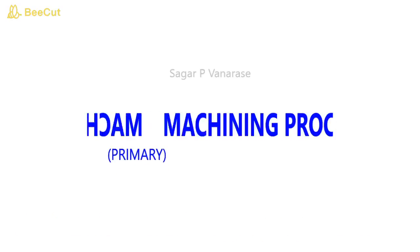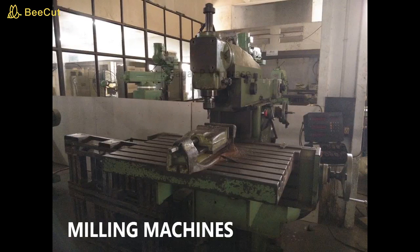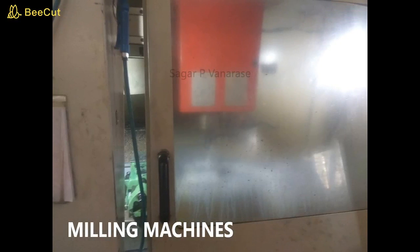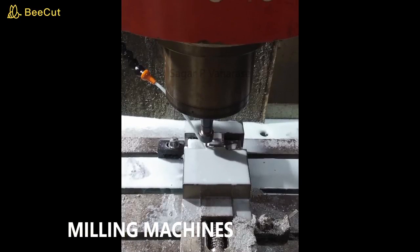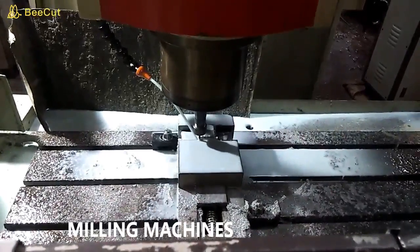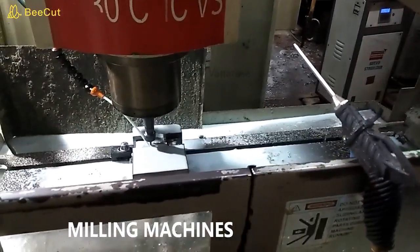The next part is the machining process, starting with the primary machining. Milling machines are used to cut the metal platens as per the drawing or design of the mold. The milling machine types are conventional, VMC, CNC, etc. In this, the NC program generated by CAM software is used, with M codes and G codes.